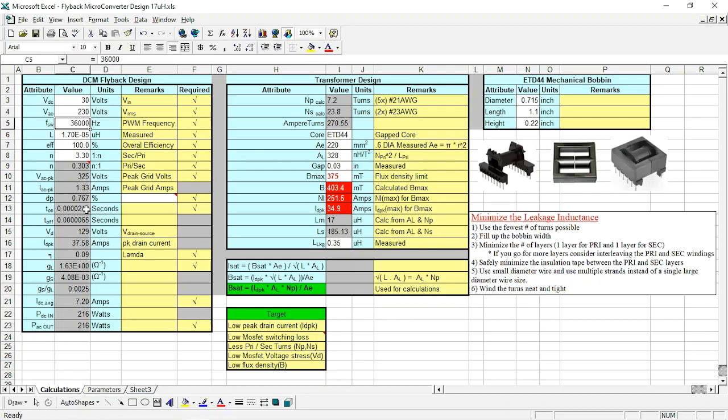One is the PWM resolution. Another is, it allowed a 20 millihenry output smoothing inductor to really smooth up the waveform. And then finally the switching loss, right? Because the higher you go in frequency, the more switching loss you get. So 36 was for me the top end that I was willing to go to.